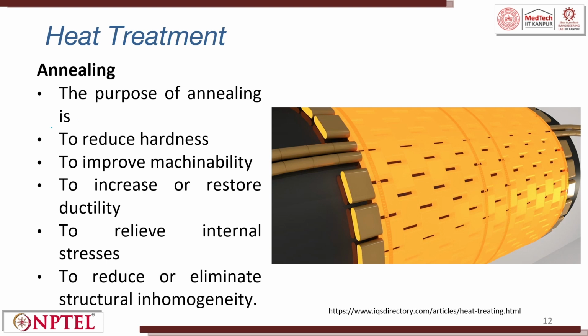The purpose of annealing is to reduce the hardness, to improve machinability, to restore ductility, to relieve all the internal stresses and to eliminate structural inhomogeneity. So, for doing all these things, we always anneal the given sample.